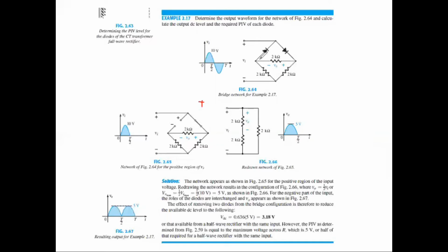Basically, here we have a bridge circuit, but in this bridge circuit we have two diodes. For the positive 10 volts peak voltage sinusoid signal, we have the positive cycle, and for this positive cycle this diode will be modeled like this one, and the current will flow here. When the current reaches here, it will be divided at these 2 points.